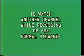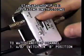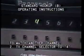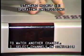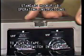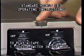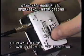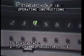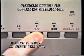Now what if we want to watch another channel while we are recording or for normal viewing? Well, the first thing we do is to put the AB switch into the B position, then to set the TV channel selector to channel 4, and finally you can view all of the channels with the channel selector on the converter. Okay, and then finally, Paul, if we want to play this tape back. Put the VCR output switch into the VCR position, put the AB switch into the A position, then set the TV tuner to channel 4, and just start the tape.